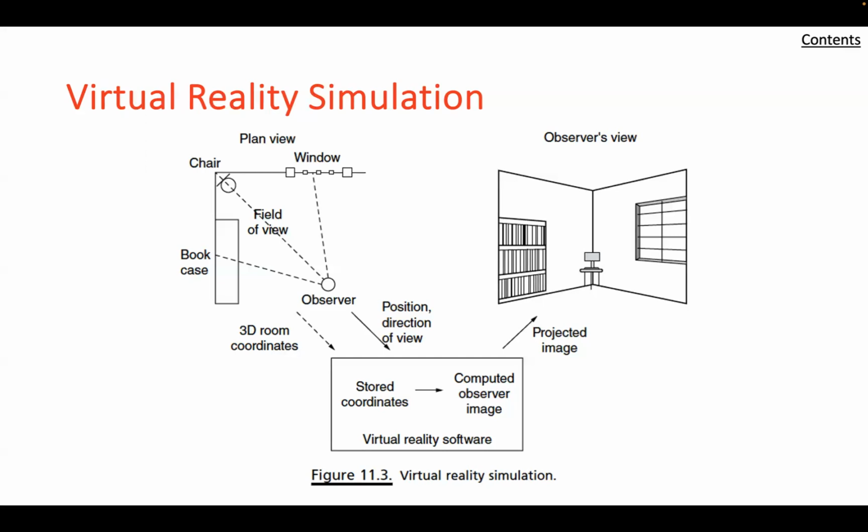So, spatial simulations. A spatial virtual reality simulation is often used when it's important to visualize the interior of enclosed spaces and the connecting exits and entries of those spaces. Computer programs exist that permit the rapid design of these spaces and the interior furnishings. A virtual reality feature makes it possible for an observer to, quote, walk through the spaces in any direction. This type of model can be used for preliminary design of homes, buildings, control centers, storage spaces, parts of ships, and even factory layouts. An auxiliary feature of this type of computer model is the ability to print out depictions in either two-dimensional or three-dimensional forms, including labels and dimensions.